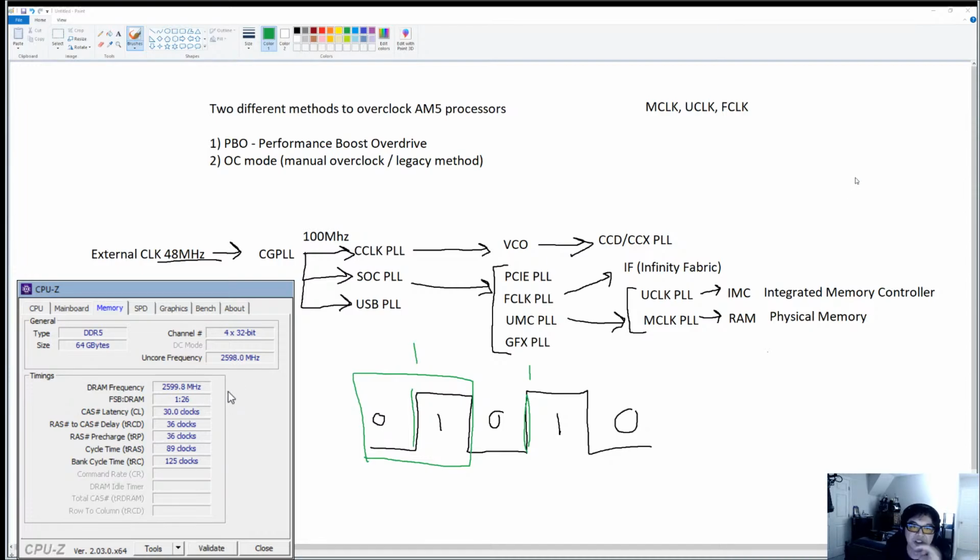This is on DDR5, but this is like 1T if you're thinking of DDR4 terminology. So that's effectively 1T with DDR4, but this is the same sort of deal. They call it synchronous mode for DDR5. So your uncore, or I guess your IMC, and your DRAM run at the same clock.